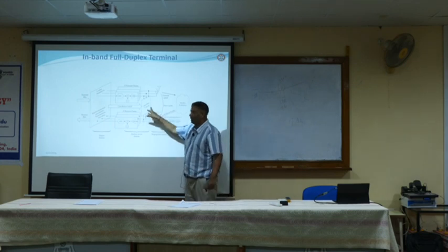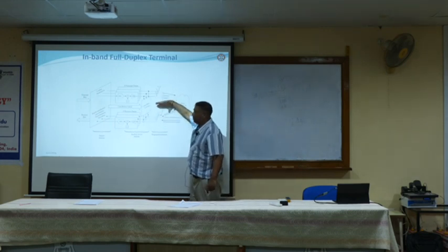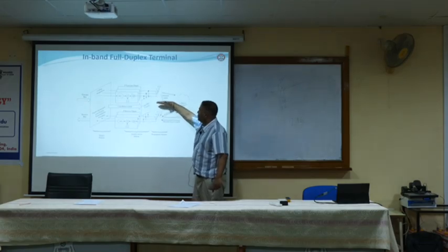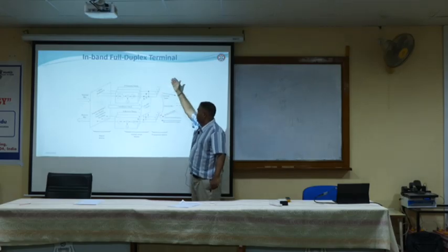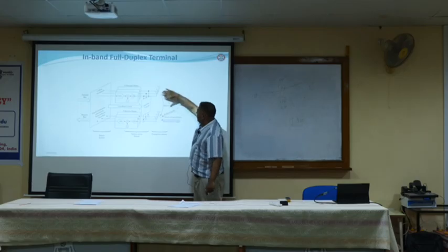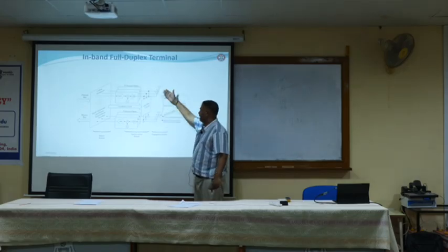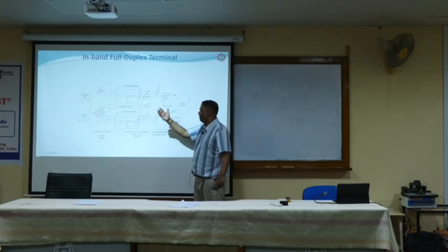Absorbing material can be put between the transmitter and receiver to stop some of the direct path, or you can do transmit beamforming such that the radiated energy is not going in this direction. So this is a kind of antenna cancellation.